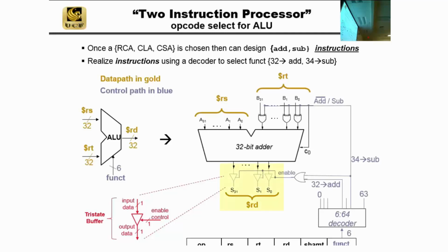Okay, so now once we've got the output here, remember, as I said, this is an adder, which is doing addition and subtraction instructions. All right, this is for ADD, right? And then we had SUB. Also ADDI and SUBI. The only difference is we're going to take a constant here. Suppose this is ADDI. Well, what would you do here? You would take the op, actually, it is going to come into here. And then you have 16 bits that's going to be added over here as a constant. The 16 bits is going to come up here.